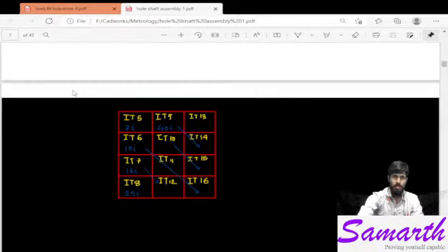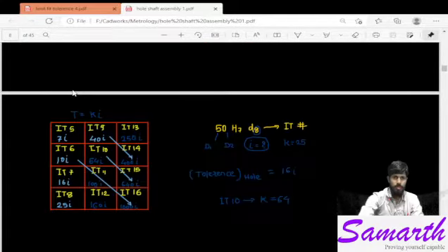This is how to keep this table in mind. You can remember it like this. You can see these arrows here. In the first row, you have to keep in mind the columns IT5, IT6, 7, 8, 9 like this. These are in increasing order. IT5 is 7i. No doubt this chart will also be given, or the IT value will be given. But for your information, to remember, the first values are 7i, 10i, then 16i and 25i. Just these four values you have to keep in mind.